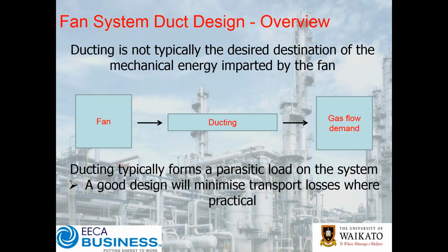Now, of course, the other side of the coin is that various systems will typically have some sort of cyclone or dust extraction baghouse, if you will, as part of them. Especially nowadays, tightening environmental resource consent constraints mean that emissions into the atmosphere are much more tightly controlled. And the reality is bad duct design can make a really good cyclone or baghouse perform really badly, whereas if you get the ducting right, generally these pieces of kit work just that much better.